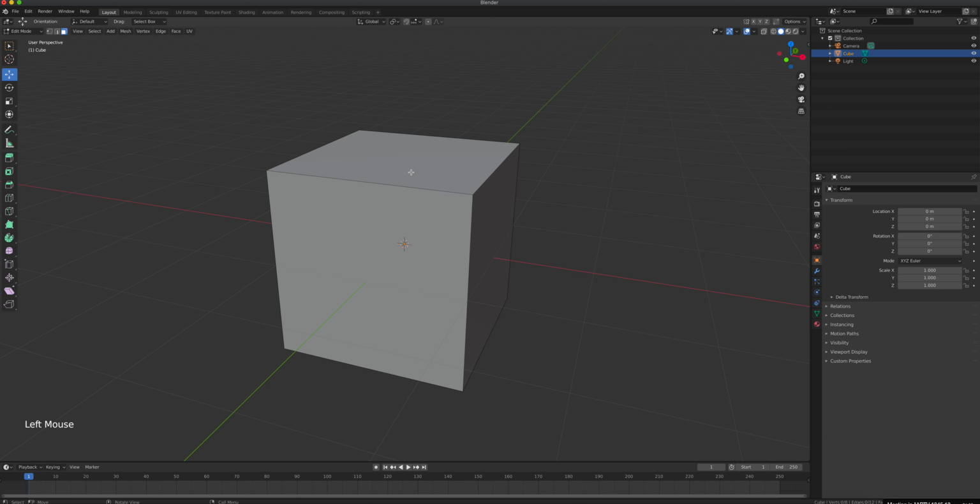Okay, so now we're selecting the entire surface, and you can add and subtract your selection by holding down Shift to add. Okay, and then holding down Shift to also get rid of the selection. So let's say I go to point mode and I wanted to select this point. I hold down Shift and I can add to my selection.